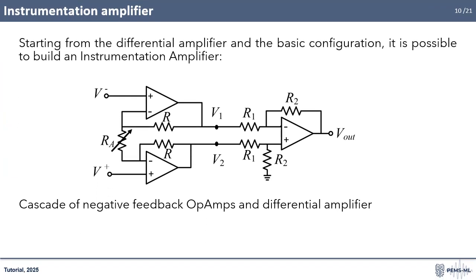One may add a buffer at the input of V1 and V2 to also overcome these last problems. However, the operational amplifier has a characteristic that limits either its bandwidth or its gain. In particular, the GBW gain bandwidth product is fixed, which means that if we increase the gain, we should reduce the bandwidth and vice versa. For this reason, it is useful to increase the complexity of the differential amplifier, not by adding simple buffers, but by adding two more amplifiers, as in the figure.